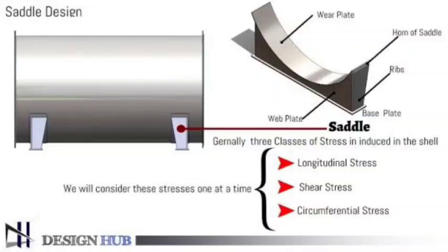So Ravi, we can conclude like this. If we face such a situation, there should be three options. First option is increase your wear plate width to the minimum recommended. If that solves it, that is okay. The second option, next step, is increase the saddle angle.